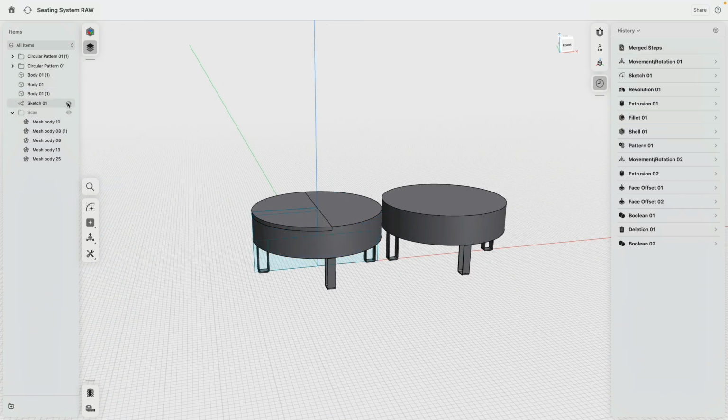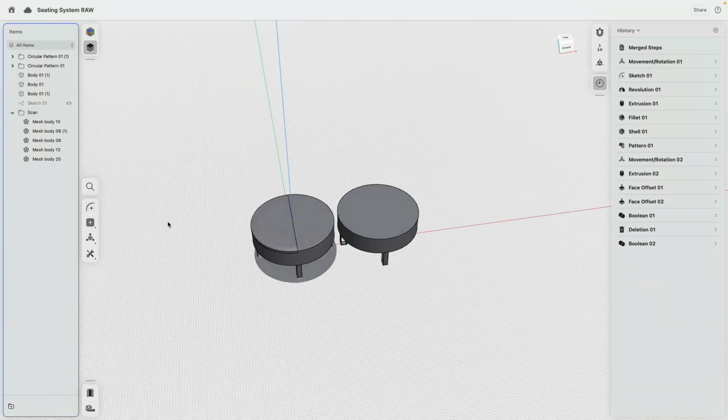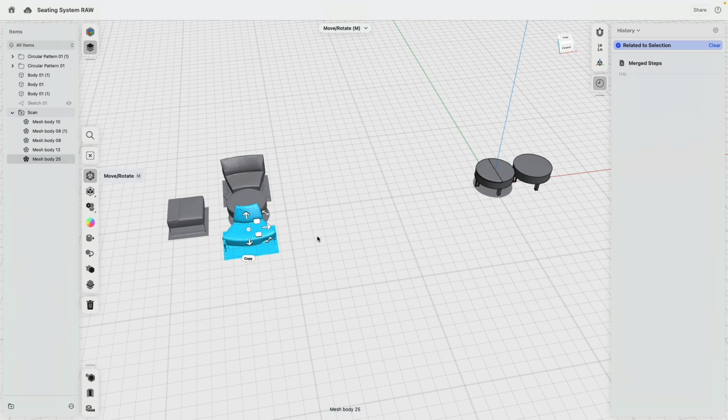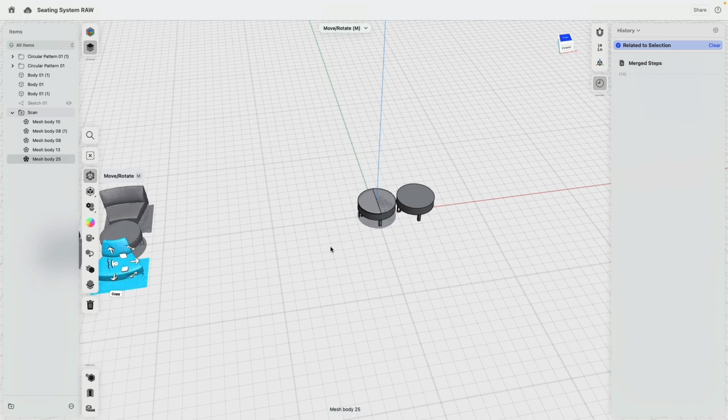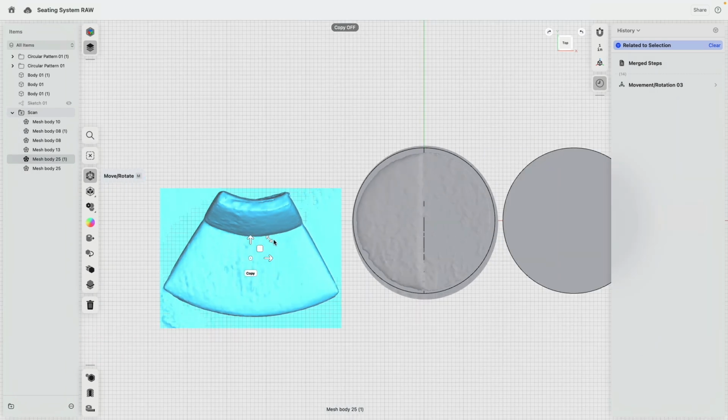Okay, very good. So you can see actually already how very quickly we developed these two pieces out of just one single sketch. Because step by step, we started adding to it. Very nice. So let's say the one is done. And we're going to work on this one now. We figured out we can put 6 pieces around. 360 is now 1 turn divided by 6, it's 60. So that means we will select this one, make a copy, bring this over, turn copy off.